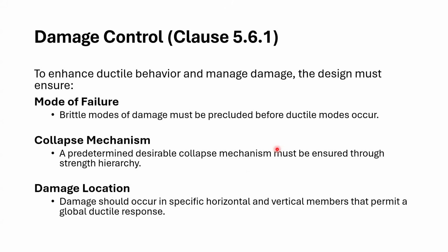Then we have the damage control clause. So we need to identify the mode of failure during the analysis stage, the collapse mechanism that it should follow, and the damage locations where it should occur. And that should be a global ductile response.